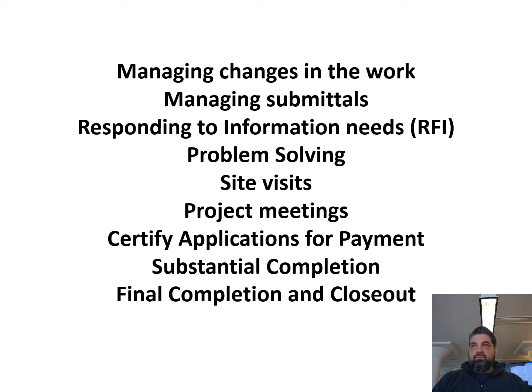And so you will issue that as the date of substantial completion with any outstanding items, right? And then the contractor will correct those items or submit all of the final closeout documentation, and then they will submit a final payout, and then you will go back out and confirm final completion of the project and make sure that you conduct all the closeout activities.